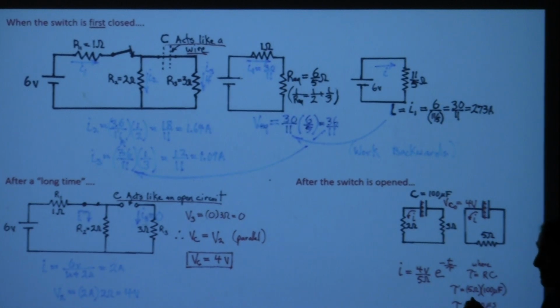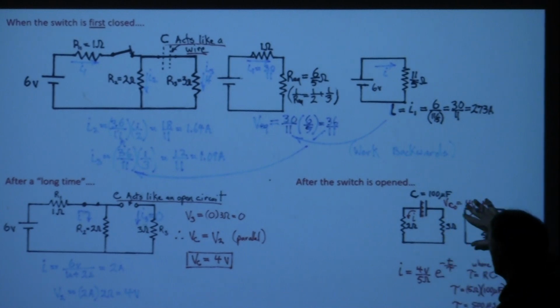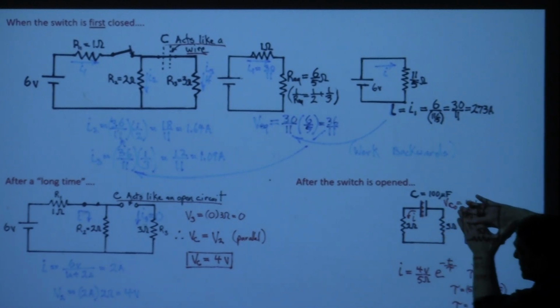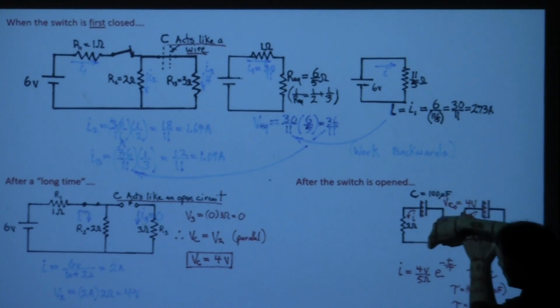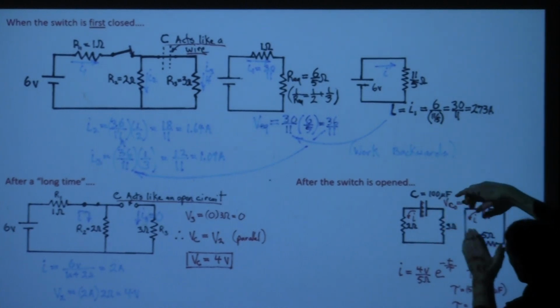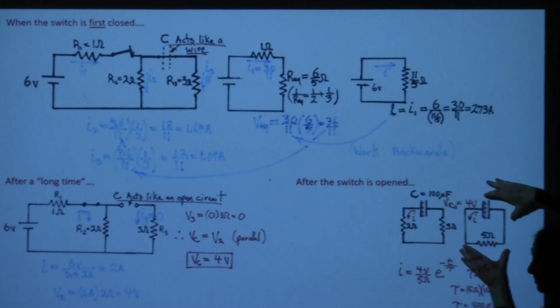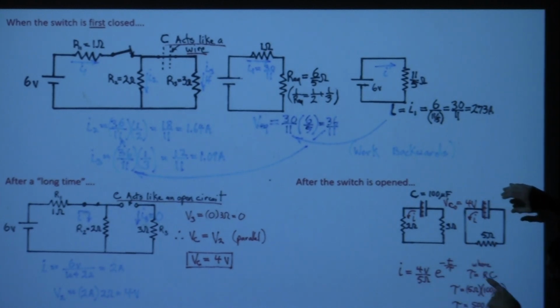Then my main question again would be, what is the initial current inside of that loop when we have 2 currents up there? Oh, maybe my picture is confusing. I'm just saying, this is the picture of what we have. And then I say, oh, these 2 are in series, so I have an equivalent circuit. This is really 5 ohms, and that's what I'll use for my RC, 5 times the capacitance.